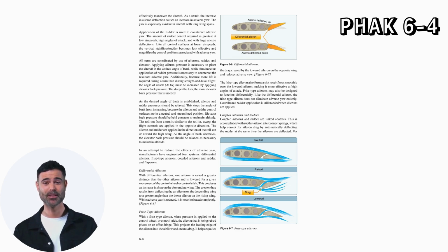Frise-type ailerons may also be designed to function differentially. Like the differential aileron, the Frise-type aileron does not eliminate adverse yaw entirely. Coordinated rudder application is still needed when ailerons are applied.